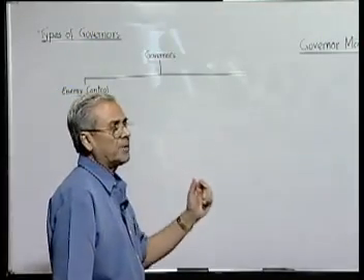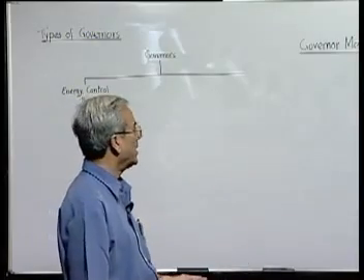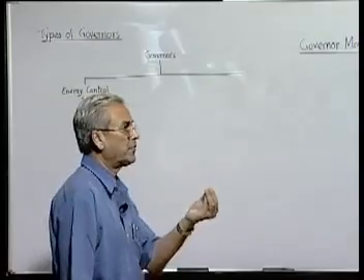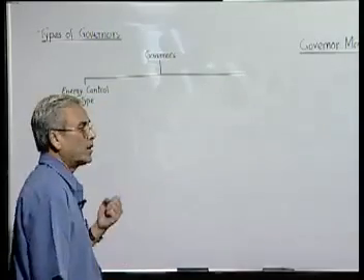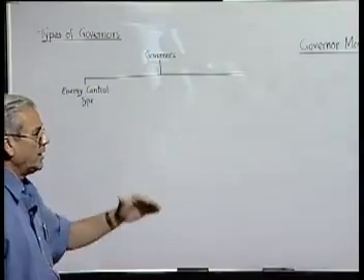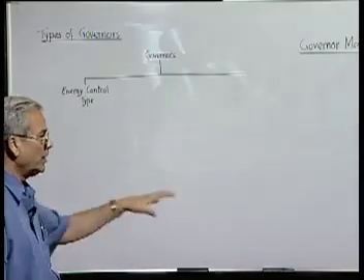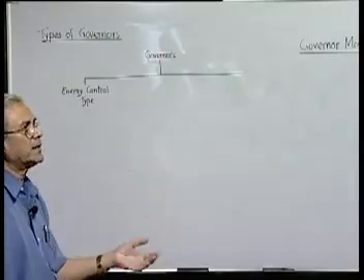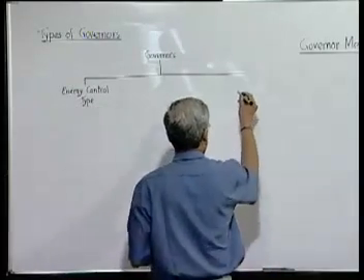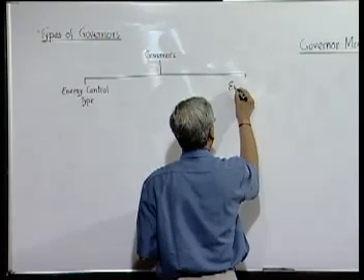Another class of governor mechanism, which we will discuss maybe in the next to next lecture, is where we don't have such an elaborate arrangement, it has to be in miniature form, or maybe the nature of the problem is such that there we always have more energy supplied. We maintain the speed by controlling the dissipation of the energy in a suitable way. These kinds of governing mechanisms are called energy dissipative systems.